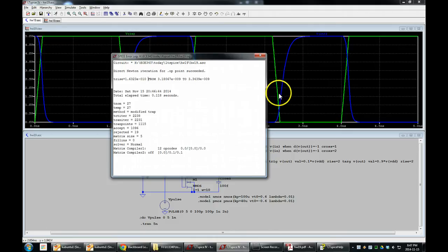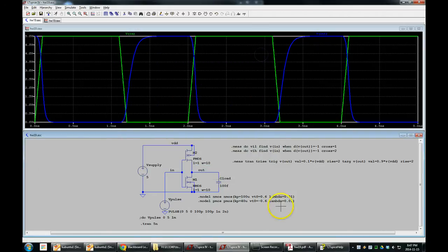We can feed in any rise time into this gate, rise and fall, because it's a pulse source. Really, these inputs to logic gates are coming from the outputs of other logic gates. So we need to set these rise and fall times that we're driving our test setup to be about the same. To do this even better, what we would do is use one inverter as a buffer, and then copy paste this over here.